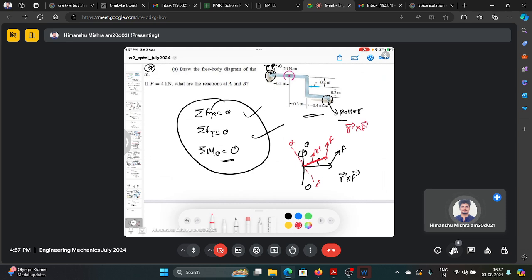So this is your new movement along O dash, and this will be your movement R dash cross F. But this is the thing: how to define this R dash vector here? Even here you have shifted that F. How can F be shifted there? It can be transmitted along a particular line. That's okay. But how have you shifted it to the other side?